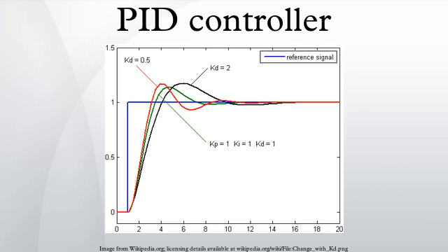Designing and tuning a PID controller appears to be conceptually intuitive, but can be hard in practice, if multiple objectives such as short transient and high stability are to be achieved. PID controllers often provide acceptable control using default tunings, but performance can generally be improved by careful tuning, and performance may be unacceptable with poor tuning.